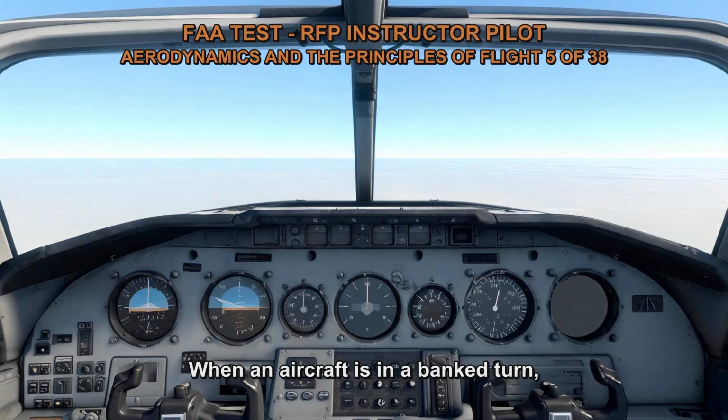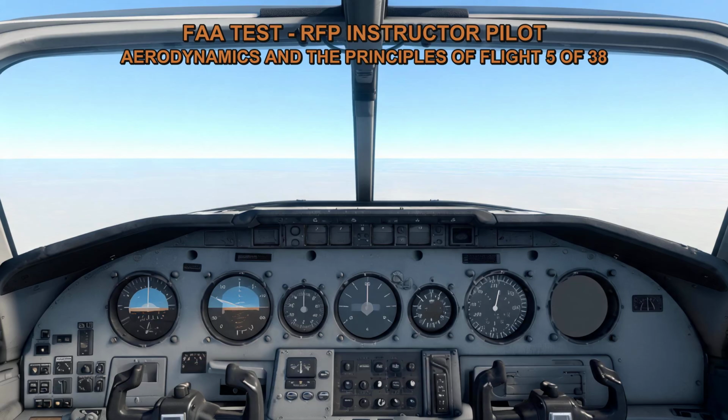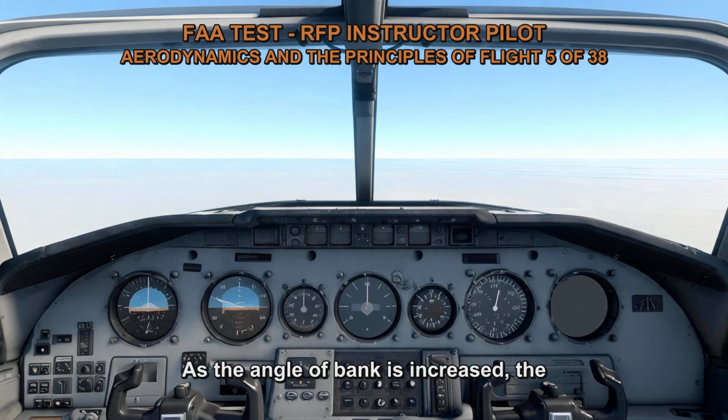When an aircraft is in a bank turn, the lift generated by the wings can be resolved into two components, the vertical component and the horizontal component. The vertical component of lift opposes gravity and supports the weight of the aircraft, while the horizontal component provides the centripetal force necessary for the turn. As the angle of bank is increased, the vertical component of lift decreases.